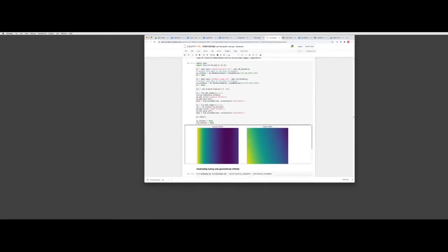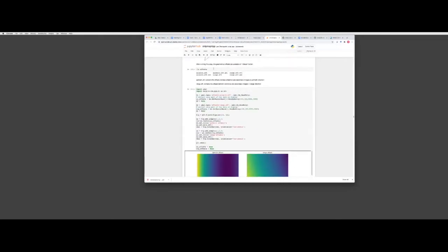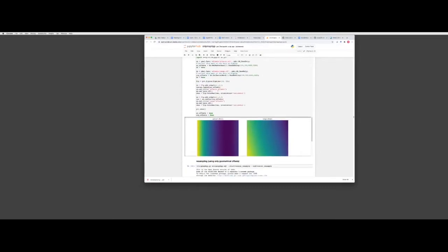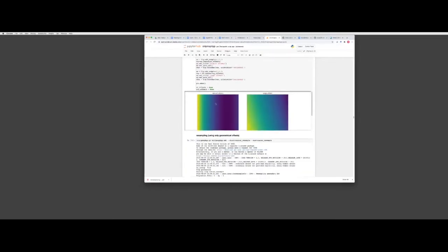It's two datasets. The output is stored in a directory called offsets, and we have azimuth.off and range.off. Again, they are rasters, so you can use GDAL and matplotlib to display them. We have the azimuth offsets here and the range offsets. You see the azimuth offsets are varying a lot, between 12 to 30 pixels. The unit is pixels, and the range offset is around -2 to -1. This is for a subset.